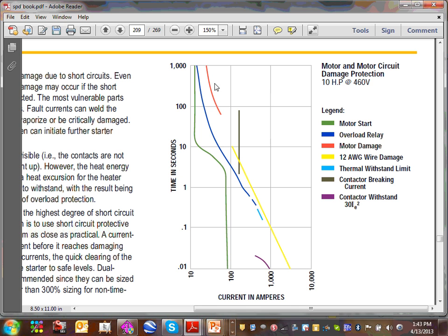Okay. I don't know how many of you guys have seen the overload relay. Can you guys see that blue? The blue stuff is your overload relay. Yesterday, my friend, you guys were talking with Jeff. That's what Jeff was doing with you. And we were sizing the overload based on 115 or 125, right? Based on the service factor. So this is, I believe, sized based on 115, right in here, my overload.